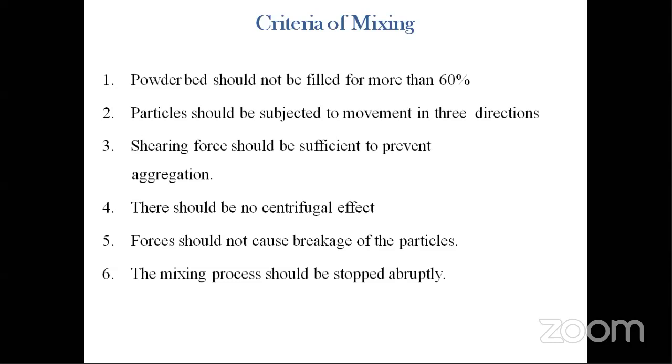So you have to make a proper shearing force during the mixing, which prevents the aggregation of the particles. Your particles are not joined with each other. So it is called the aggregates, not to form a lump. So you maintain an optimum shear force which prevents the formation of the aggregation.